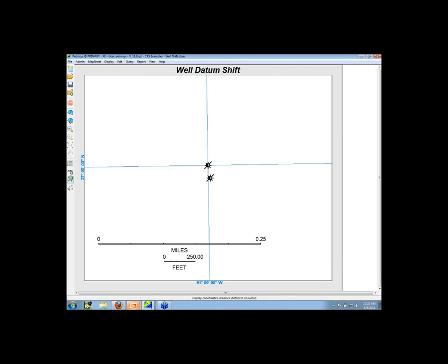As you can see, we moved there, and using our little ruler tool, I can measure that that's right about 105 U.S. feet. And I can read that data down here in the bottom in the little status bar. In Petrosys, that gives you a lot of nice information you can use, and so we can see 106 U.S. feet difference. So it's important for you to have your locations in the correct place. You're going to want to specify the correct geographic CRS.